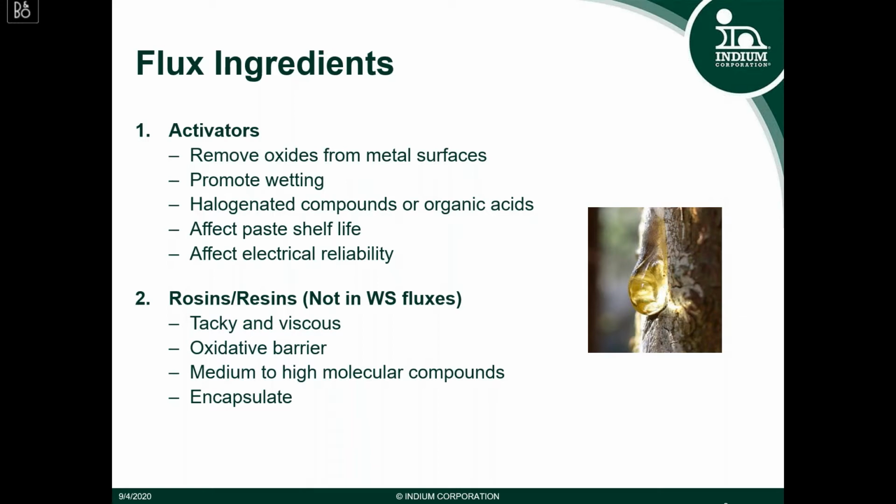The paste shelf life is dictated by the activator shelf life because over time, the activators will expire and no longer do what they're supposed to do to remove oxides and promote wetting. For electrical reliability, because they are halogenated compounds or organic acids, they could pose a threat to electrical reliability. So rosin, the second group of chemicals, is used to encapsulate those activators and keep the flux residue benign.